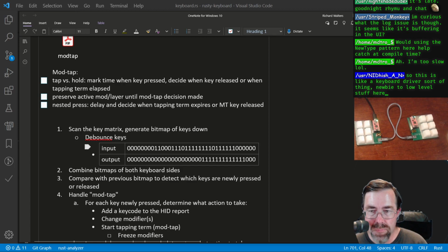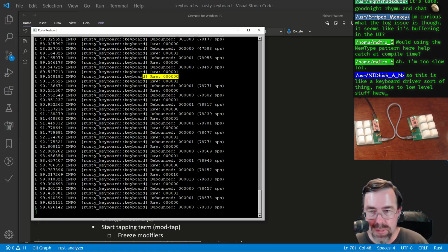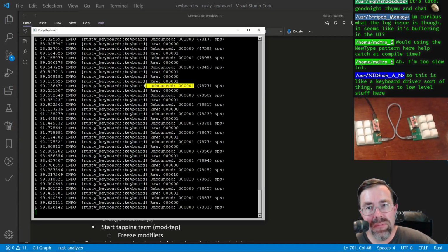So it's where the electrical signal is not stable yet. We're transitioning between it not being pressed and pressing it. We have this instability here. So the debouncing algorithm is just ignoring that and waiting until it sees a constant string of ones and then says, okay, so you must be pressing the button now because we're seeing it stable at a 1. And then here, this is an unstable, spurious zero. This shouldn't be there. And then we see a consistent set of zeros. It's like, okay, you must have released it. So that's what the code here is doing, that it's at all zeros, and then it sees one of them go to 1, and then it sees it go to 0, and then it sees it go to 1, and then it stays at a 1 long enough to say, okay, we've debounced it to a 1.